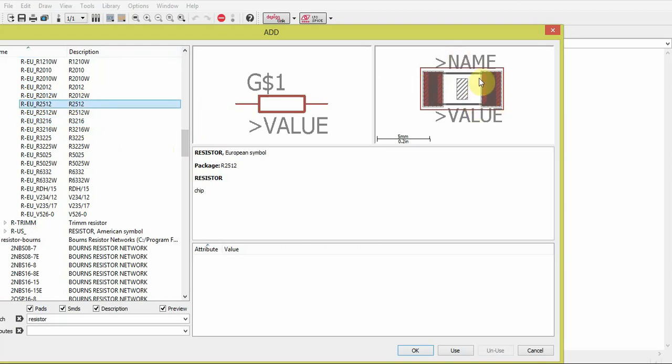So this one basically has rectangular metal pads on the component, and then corresponding metal pads on the printed circuit board as well. So you could do this on the top or on the bottom layer, depending on your design. This one, as you can see, has no leads, so there's no holes being drilled in the PCB to accommodate this component. This one gets directly soldered onto the surface. Therefore, it's called surface mount.